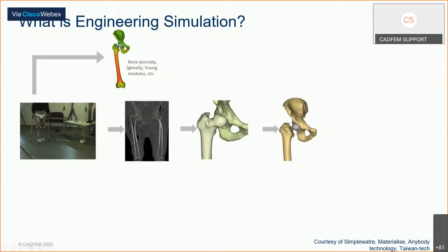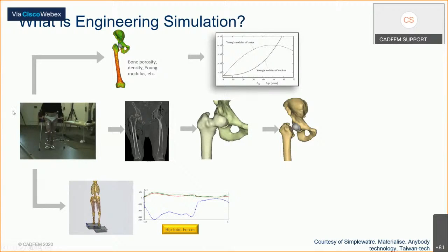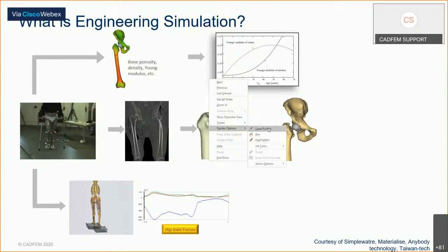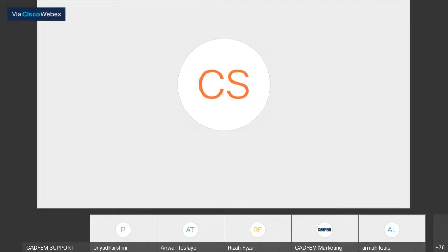It's person specific also. So you can enter all this data in ANSYS using different methods, basically giving each density through the element or through the coordinate system. You can input the forces coming onto this body part and do a test, so that you can see how the stresses are coming in the bone, as well as how your implant is behaving with respect to bone. Is it sliding too much? How is the contact pressure? All those kinds of things you will be able to see.